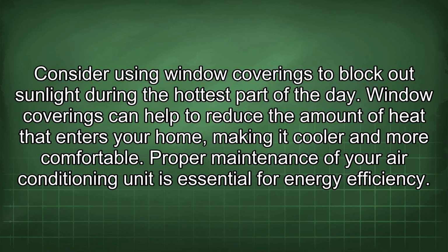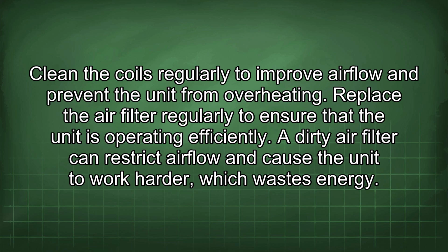Window coverings can help to reduce the amount of heat that enters your home, making it cooler and more comfortable. Proper maintenance of your air conditioning unit is essential for energy efficiency. Clean the coils regularly to improve airflow and prevent the unit from overheating. Replace the air filter regularly to ensure that the unit is operating efficiently. A dirty air filter can restrict airflow and cause the unit to work harder, which wastes energy.